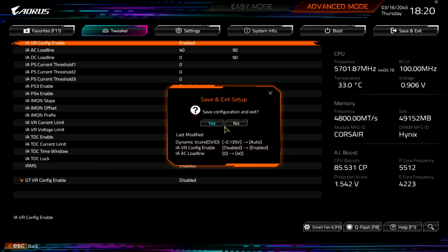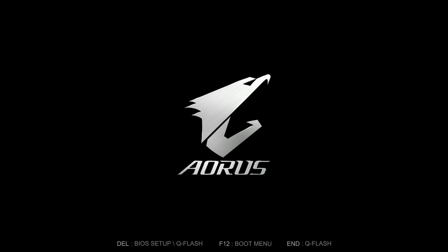Normally, with CEP disabled, this would actually crash in some workloads, not necessarily Cinebench R23, but with my CPU, a 0.4 AC load line on this motherboard with CEP disabled. If you turn the power limits on, it probably won't crash, but without the power limits, like the default Gigabyte settings, yeah, it would crash. But with CEP turned on, this won't crash. It'll just cause a massive performance reduction.